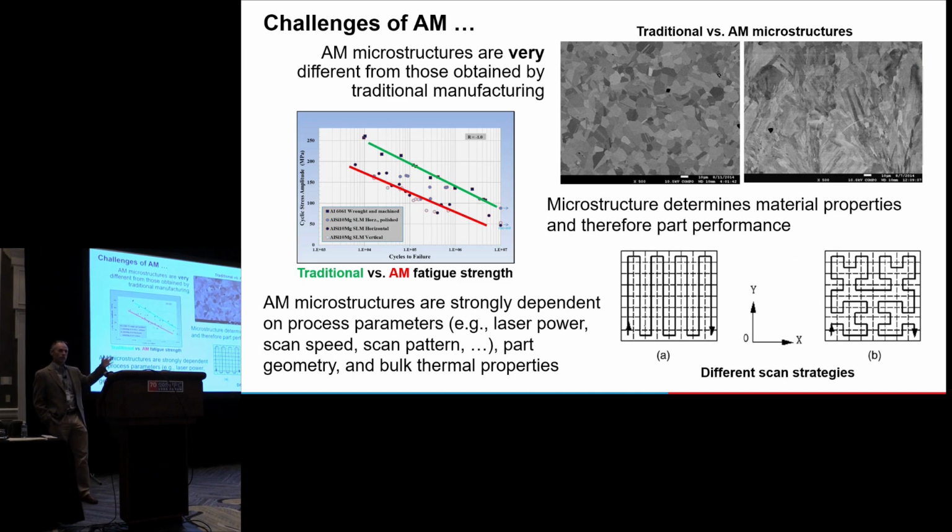And the grain structure is all over the place. It's oriented in different directions, you've got some alignment along different axes. But it's really not what you want to see. And you have unattractive material properties out of that kind of part. And you can see the strength of the parts. This is just using typical approaches. With additive, you get quite different strength properties out of the two. The good news, though, is that the microstructure that you get out of there is very controllable.